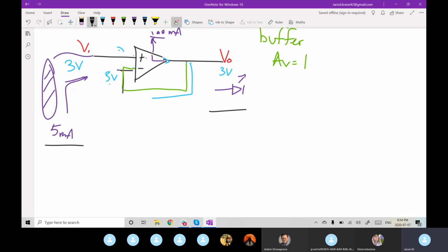You could do that. But I think it comes down to how sensitive the signal is. If you're running some super small 5 milliamp 2 volt kind of sensor, like it's something quite small, where it may not even have enough to trigger the MOSFET, the buffer would be the ideal way to go.